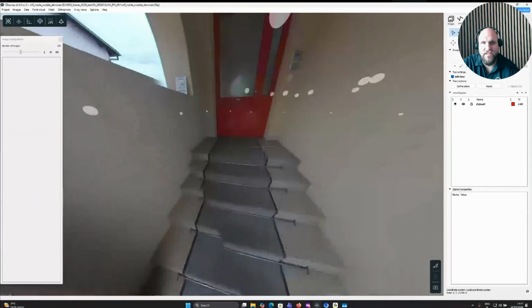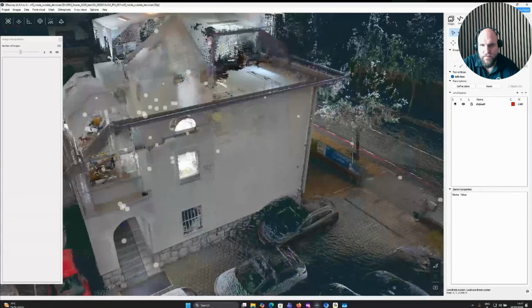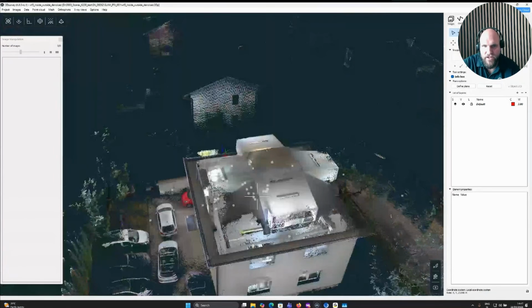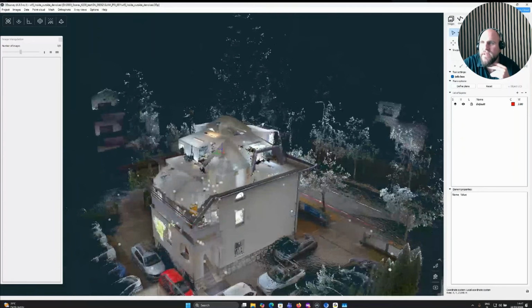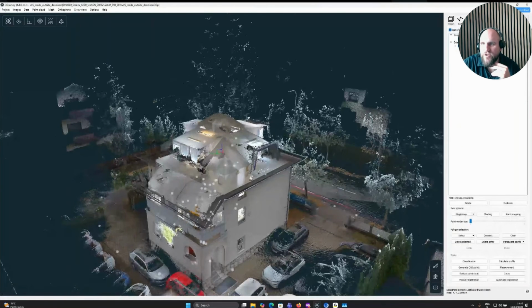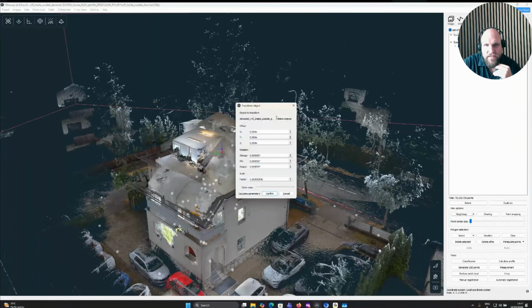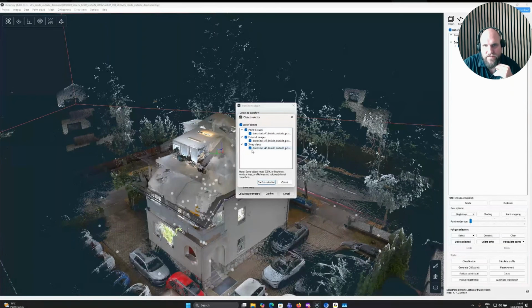So we have here this second project with the spherical images. With SLAM data, very often when we import them, we have to move them a little bit, maybe vertically, if we don't have SLAM data with the geoid model. If we come here and try to transform that, whatever is in the project and can be transformed will be in here. So even the X-ray views and everything, if they are present, if you move everything up, then everything will move vertically, or however you set the transformation here in the parameters.